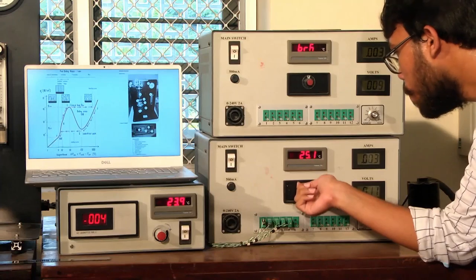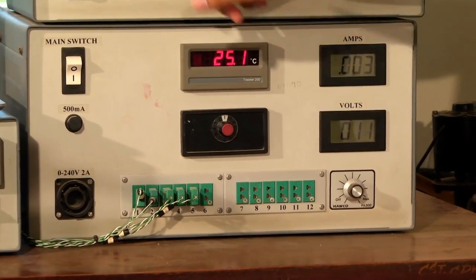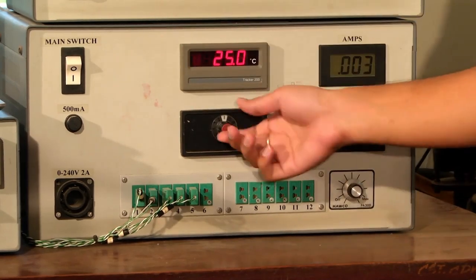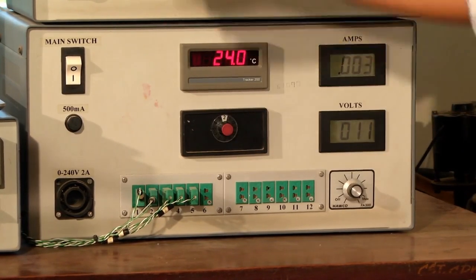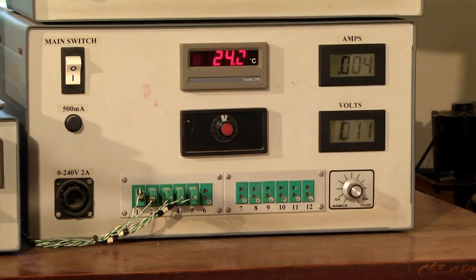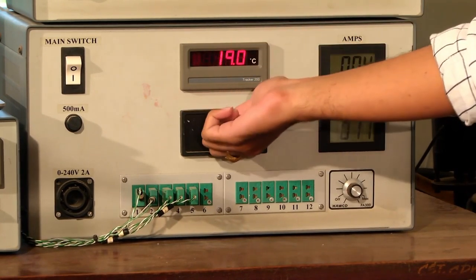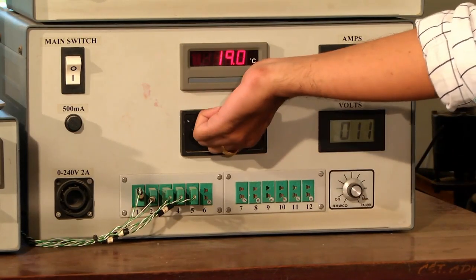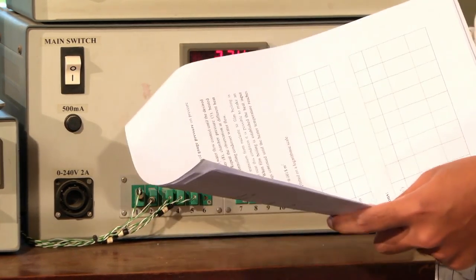If you turn the knob, here it is showing the T1, which is the solid cylinder surface temperature. It is around 25. We are not heating, so, and if you rotate the knob, you will get the T2, which is the liquid temperature. Now it is around 24, and T3 is the vapor temperature, which is around that water cooled condenser. It is around 23, and T4 and T5 are the inlet and outlet temperatures of the water flowing through that cooled condenser. These are the temperature measurements you will have in this experiment.